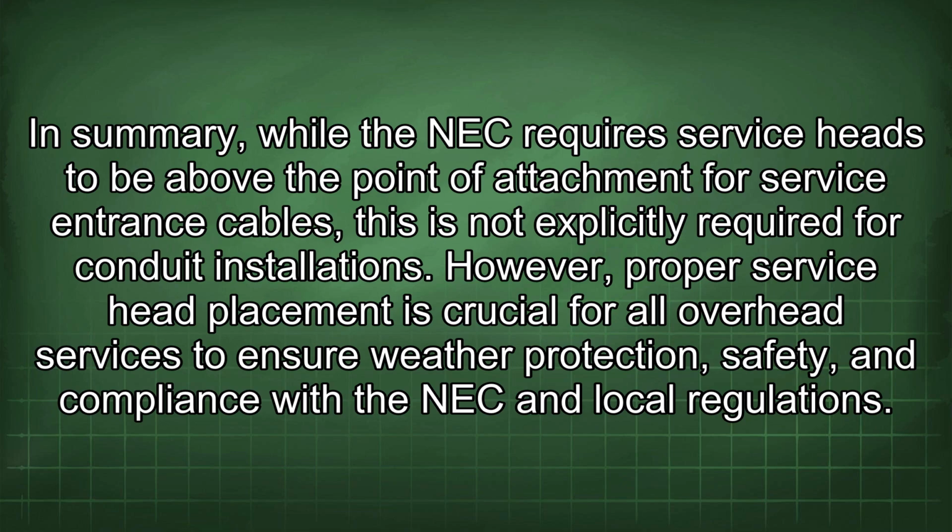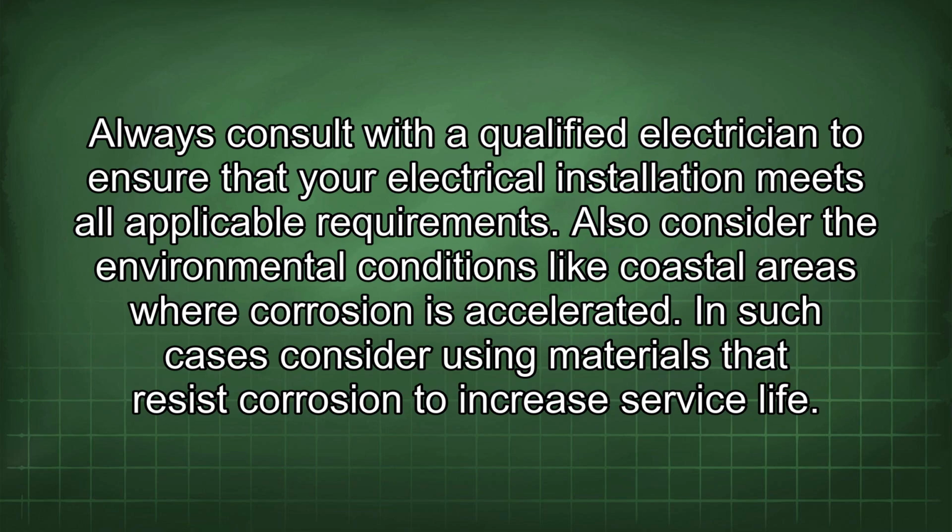In summary, while the NEC requires service heads to be above the point of attachment for service entrance cables, this is not explicitly required for conduit installations. However, proper service head placement is crucial for all overhead services to ensure weather protection, safety, and compliance with the NEC and local regulations. Always consult with a qualified electrician to ensure that your electrical installation meets all applicable requirements.